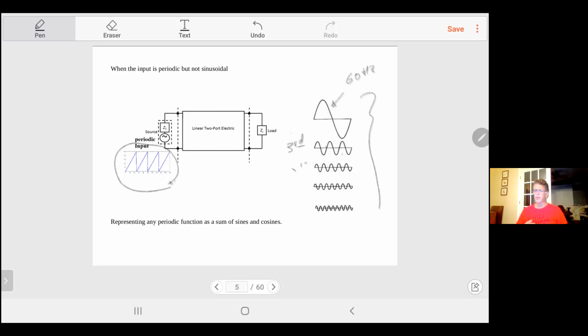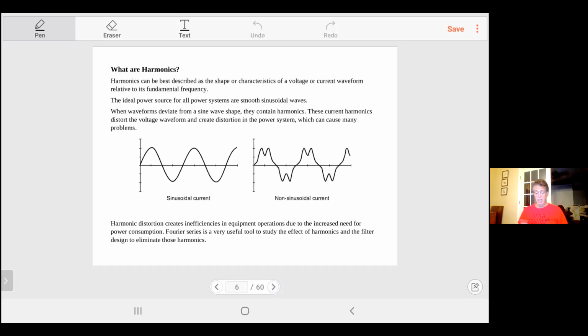So you have a series of inputs, and every time you analyze your circuit, you get the corresponding output, and in the end, you add all of them using superposition. As you know, superposition can only be implemented for a linear network, and we assumed a linear network from the beginning. So that's an application, and that's very important in analyzing electric circuits and electronics.